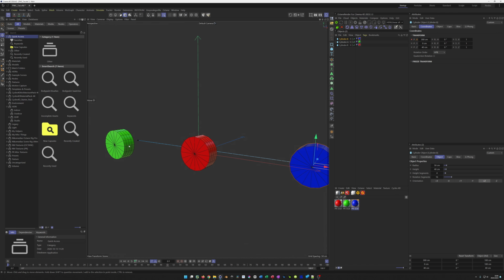So, and now we would need some holders here, so some things to come in. We can do this later. Let's first do the linkage. So, good. For the red one, I make a duplicate. So I control drag it down and have a copy.